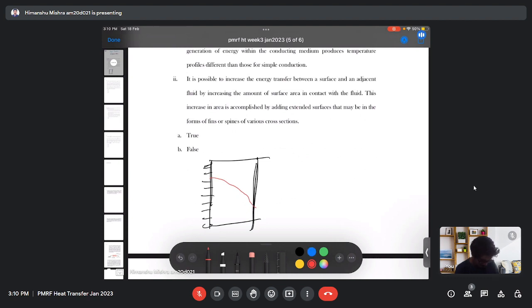There was a question as to why it is not like this or something like this for the case where the left side of the slab is adiabatic, that is, there is no heat flux at the left side. The main reason is that since there is no heat transfer at the left side, the slope of the temperature gradient here will be zero. That means dT/dx equals zero, which ensures that the heat flux will be zero at the left-hand side. And let's imagine there is a finite slope at the left.